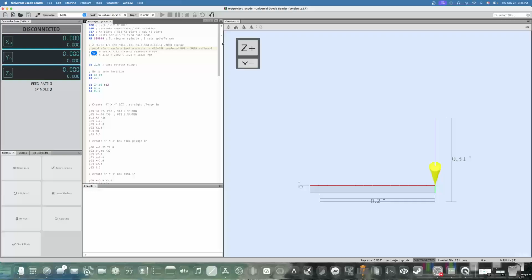You got the number of flutes, that's the little edges that cut on the end mill. You got the chip load, which is actually what you're feeding. That's the amount of material one edge takes off what you're cutting per one revolution of the spindle. And of course, the last one is your RPM. So if any one of those 3 variables are different, then your feed rate will be different, and often drastically.